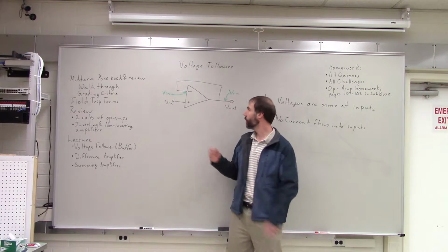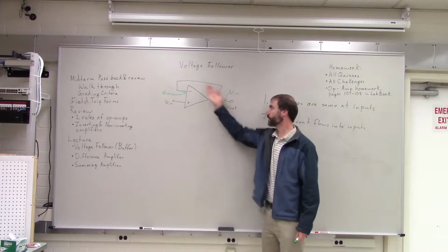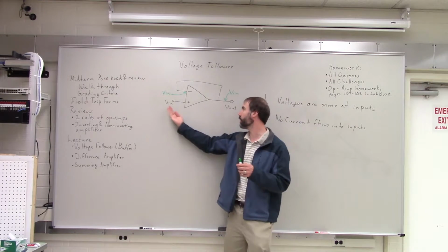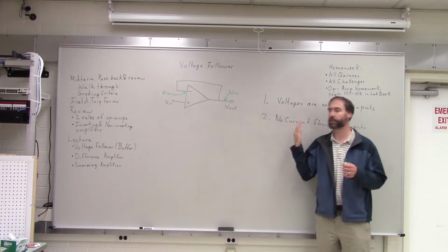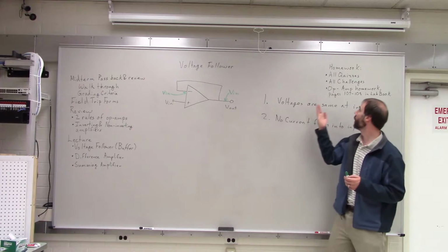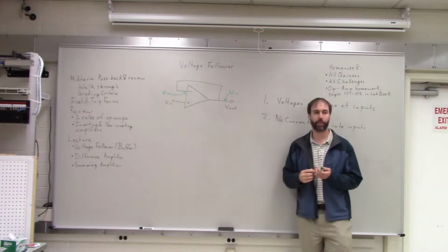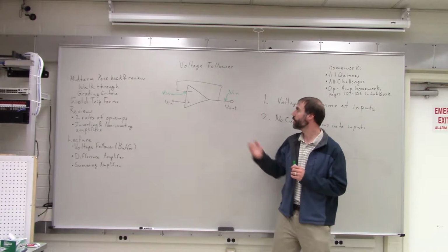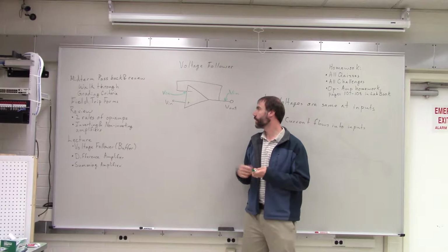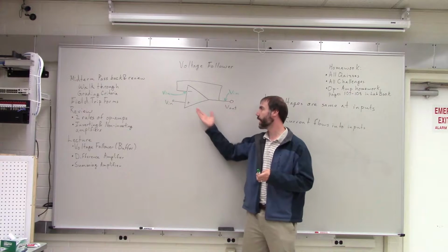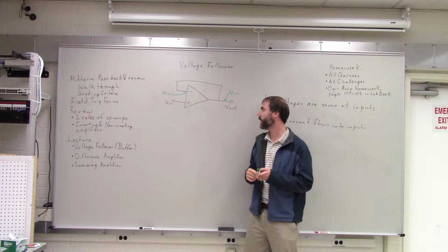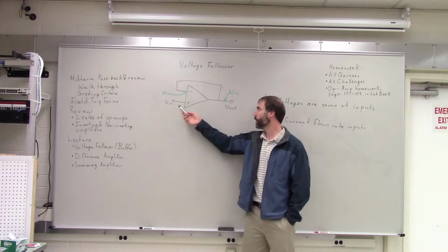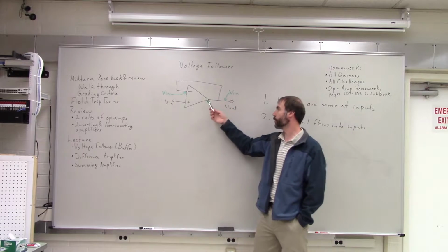Okay? So this circuit can provide a buffer, sort of a guard between your weak signal and the rest of your circuitry. So that's why it's sometimes called a buffer circuit. This circuit can be used to protect very weak signals. Another way to think about it is that we know that we're not getting any voltage gain here, right?